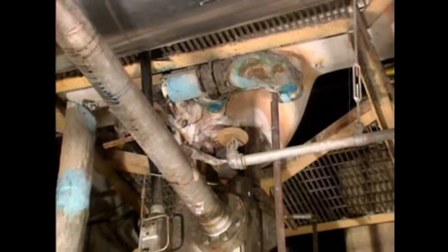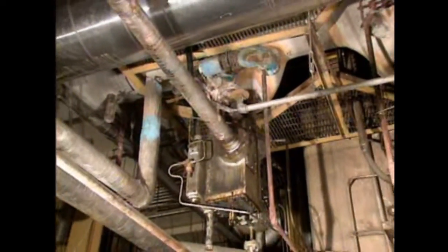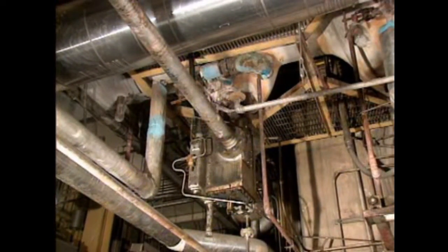If the turbine begins to speed up, the control valves will compensate by closing. However, there is still a great deal of steam in the reheater section of the boiler. This steam will continue to flow through the turbine, causing it to speed up. To prevent overspeeding, the intercept valves close, cutting off steam from the reheater.